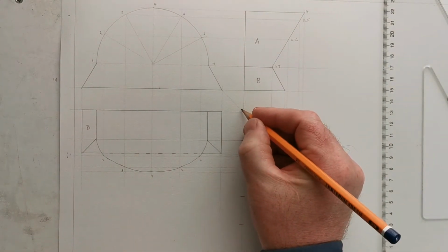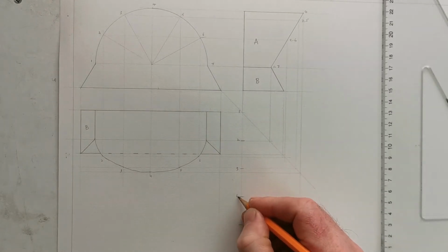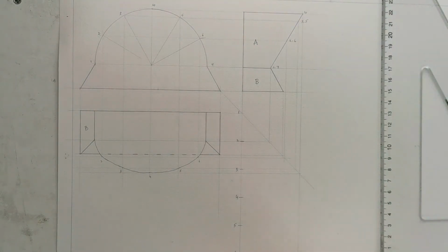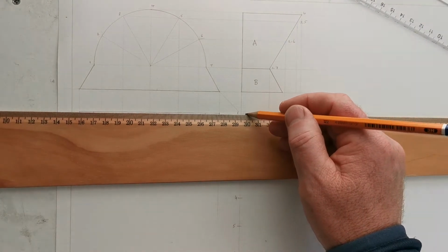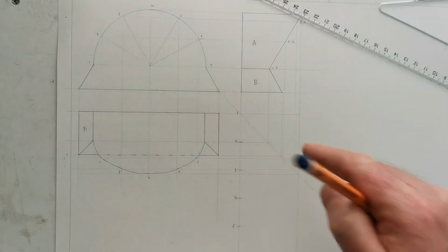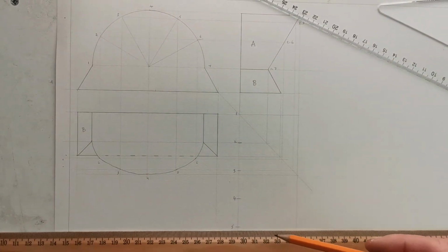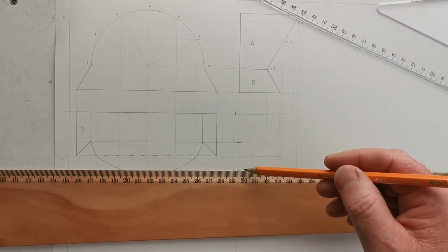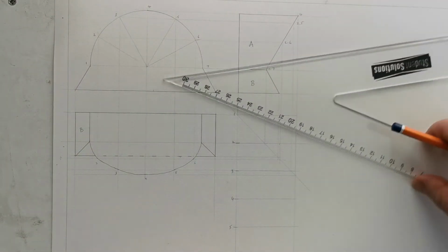So if I'm starting off here with this one, I'm going to say that that's 1, 2, 3, 4, 5, 6, and 7. So if this was a full semicircular roof, it would be just a rectangle like this. Okay, but it's not because of this curvy slope cut out of it. So I'm going to just draw light lines up from all of these, and I'm going to project down here in a second where each of these gets cut.